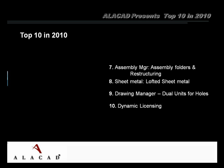Assembly manager, I can now create assembly folders, allowing me to shrink up my browser tree. I can create one called fasteners, put all my fasteners in it, organize it nice and neatly. Restructuring allows me to promote and demote out without losing assembly constraints.